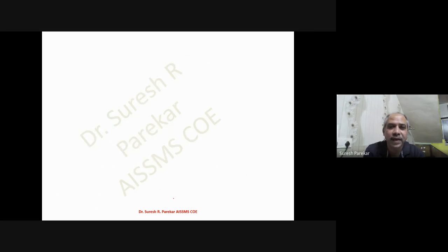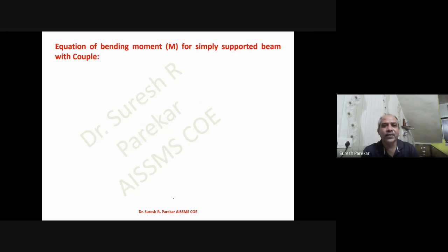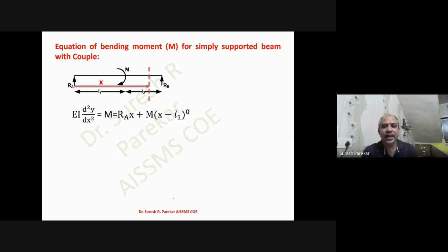So likewise, we have to go for UDL. Now, if we have a couple, then what will happen in this case? So now if we go for this couple, I will write it. Then I have RA into x. This will be my first region, so I will mention this as C. So RA into x will be between A to C. So I have this first region plus m into (x minus L1) to the power 0.